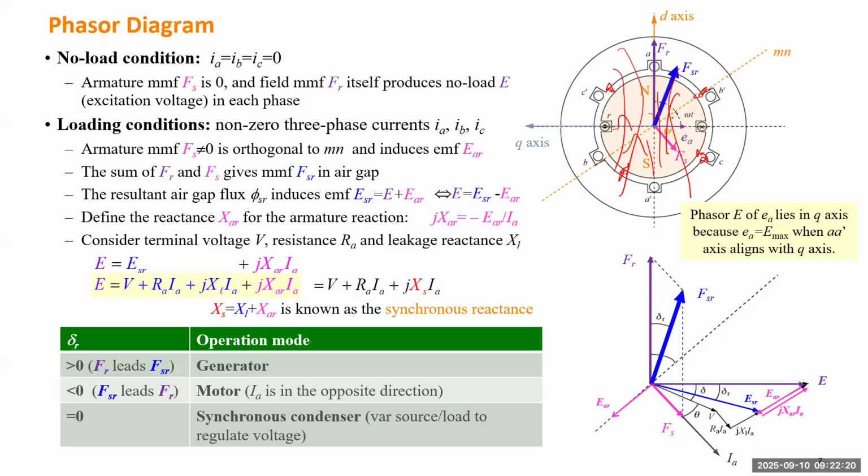Then that will induce voltage. But the flux depends on the material inside of this magnetic field. So if the inside of the stator is a fully magnetic material, the flux can be really large. But if the material is not magnetic, the flux can be smaller.